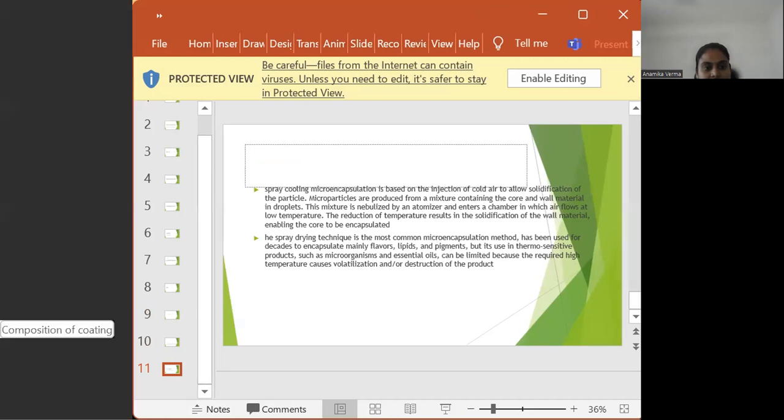The spray drying and the spray congealing methods of microencapsulation are almost similar in that both methods entail the dispersion of core material in a liquefied coating agent, or spraying or introducing the core coating material into some environmental condition whereby relatively rapid solidification of the coating is effected. The main difference between these two microencapsulation methods is the means by which the coating solidification is carried out.